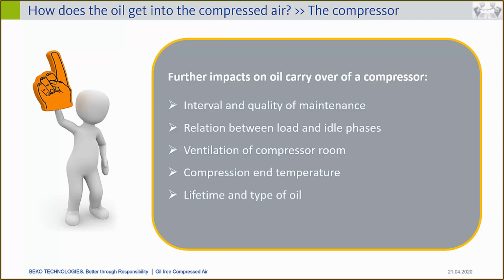Furthermore, the lifetime and the type of oil is one influence. Mineral oil and synthetic oil have different vaporization temperatures. So mineral oil vaporizes more easily compared to synthetic oil. And also the lifetime is important, because the function of the additives is the critical point here.